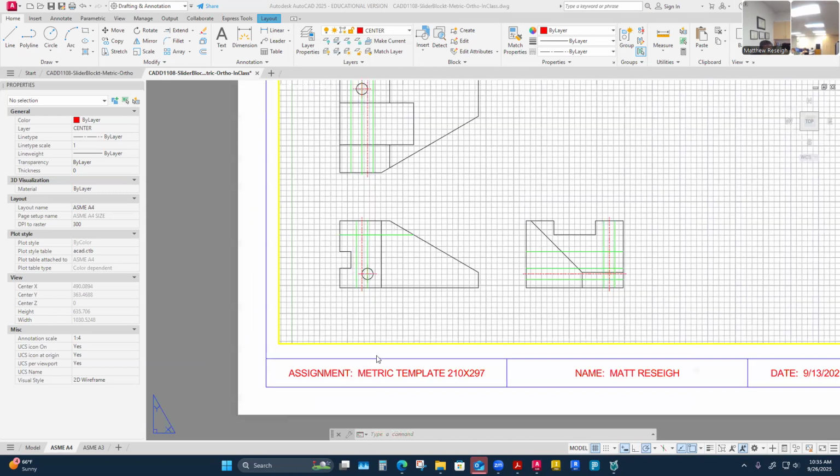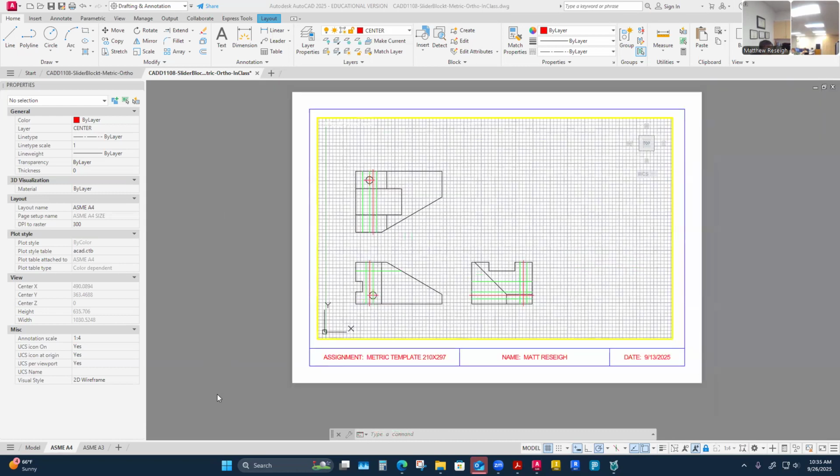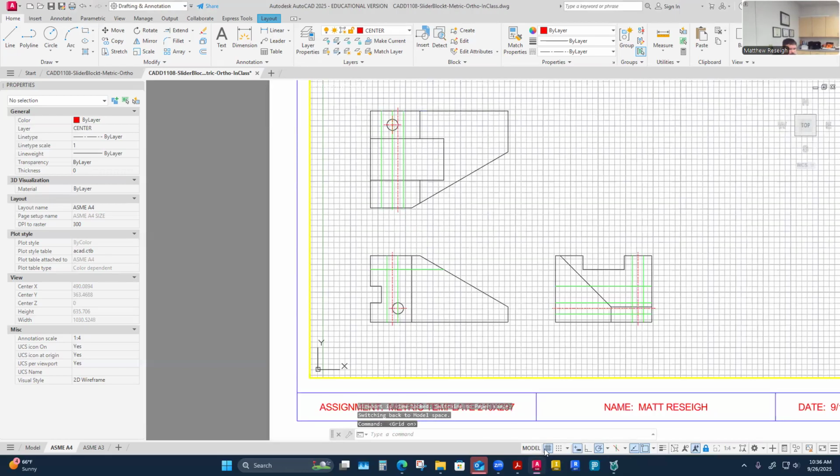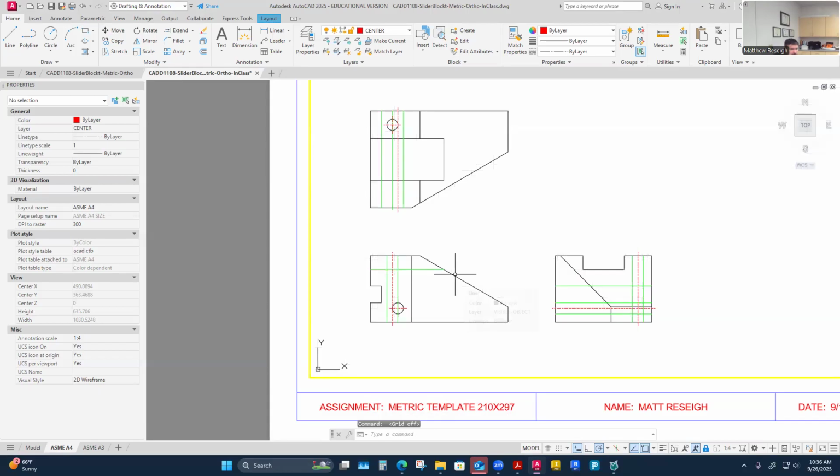Let's see. Let's finish. So yeah, this is where I think I've determined I would keep my half scale. I'm probably going to go to the A3 size sheet on this one. And this is where I can now determine my line type scales for these, before I dimension maybe. So I will look at it from here, but this grid pattern's a little bit busy, so I'll turn off my grid. That's what you always have control over when you're in the model space through the viewport. It's still going to look like I'm on paper though. I'm not going to zoom in until I go to dimension it. Out here is where I generally look at my line type scales, out here on paper. It's just my habit. It's not that you have to do it any particular way. So I'm just going to turn off the grid because that makes it harder for me to tell.